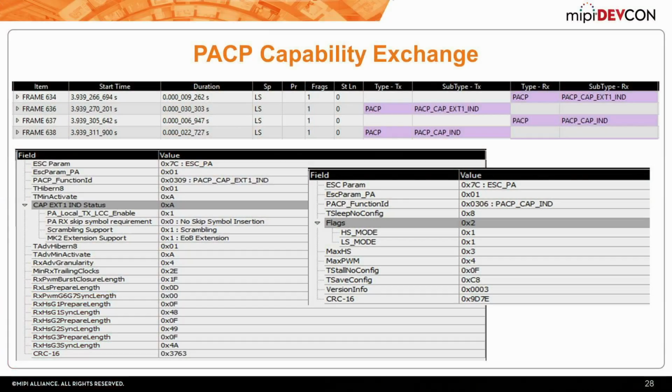So here's an example, a trace of a system that's coming up. These are physical layer and layer 1.5 capabilities that are shown in the PSEP frames as the link comes up. So these are capabilities, and this is what kind of capabilities are in there. Which high-speed modes does it support? You'll also see, does it support scrambling? Which rates does it support? That kind of stuff. You can see there's one in each direction, the upstream and the downstream.